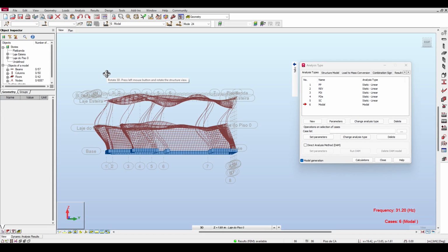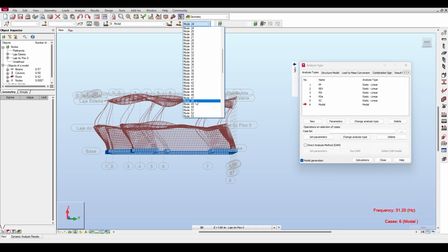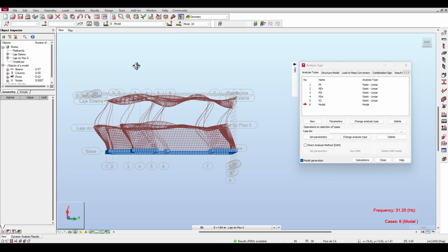You are going up to frequencies of 40 and 50 and 60 Hertz and whatnot, and it becomes kind of unfeasible to vibrate the structure like this, because why do we do a modal analysis? We do a modal analysis because we want to check if there are, for example, resonances, if we want to use the modal decomposition, and it kind of makes it harder and harder to vibrate structures at those frequencies. So, I don't know how to say this, but I would be very satisfied with 80%, and that's it, and just leave it like that.